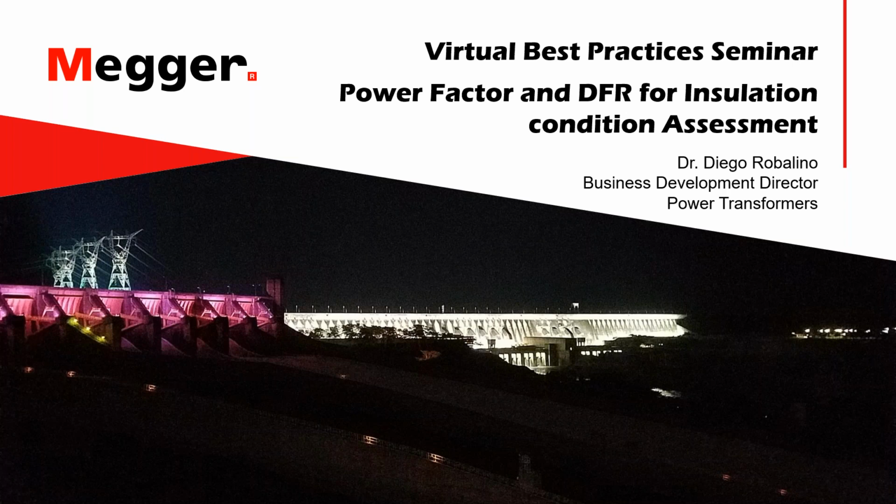But as he mentioned before, power factor is not only for power transformers, it is for instrument transformers, cable, motors, any kind of insulation, liquid insulation, solid insulation. A power factor piece of equipment can help you analyze those results and provide some condition assessment.